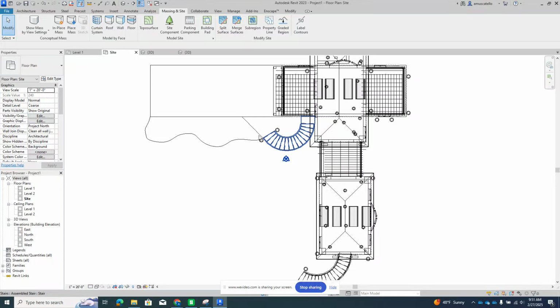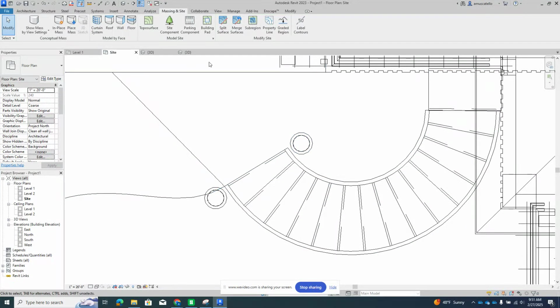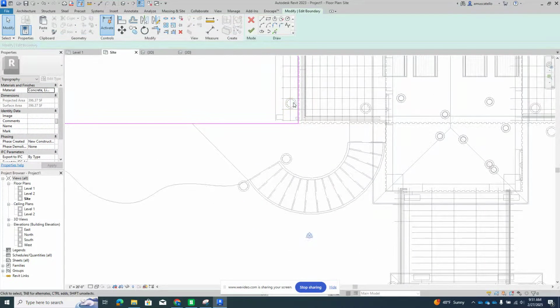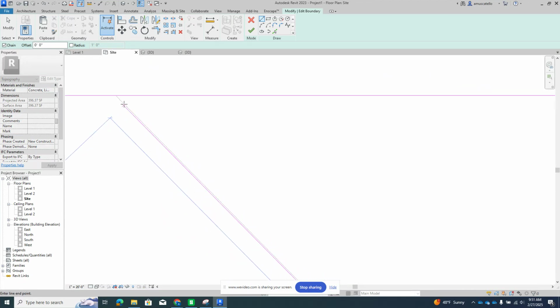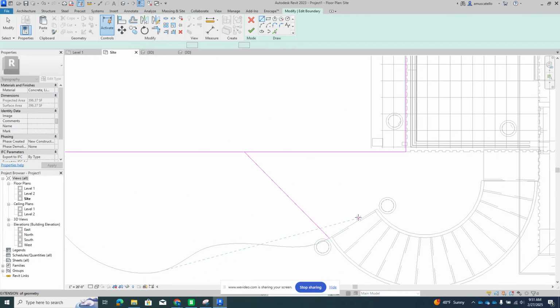Okay, and you can see that I have a new subregion that I've moved, and now I can create a sidewalk here if I'd like to attach to that concrete. I could also edit my concrete since it's already a concrete driveway, and I won't have to create a new subregion. I can come in here and use the line tool, connect, let's cross, and let's just do that.